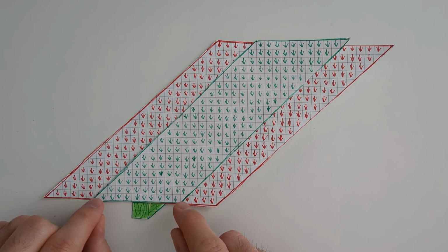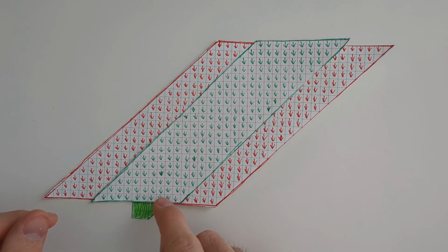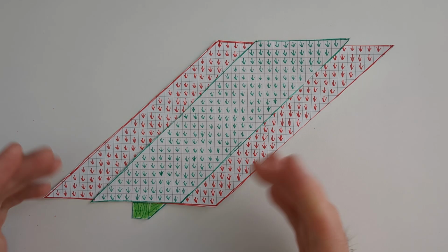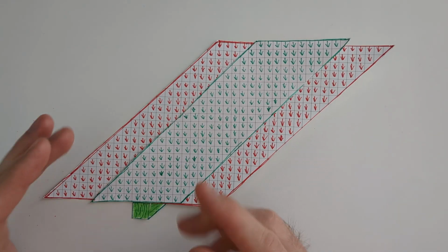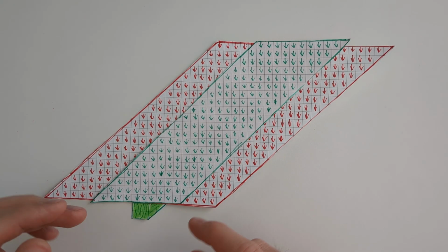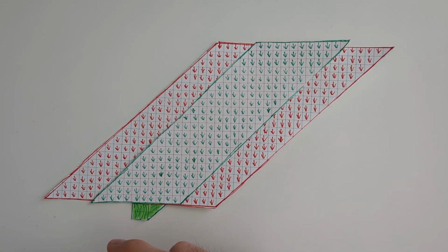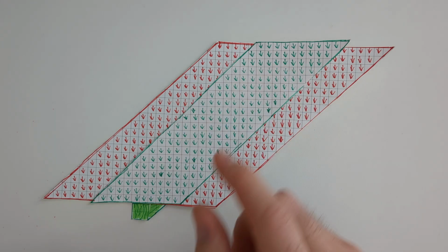So in each foot, we'll take these arrows and compress it. And you can see here, each foot is represented by the square. So in each line here, we have 1, 2, 3, 4, 5, 6, 7, 8, 9, 10 arrows. So if we compress it, that means within each foot, we'll have 10 arrows acting down. Now, if each arrow is 50 pounds force, we have 10 arrows. That should be 500 pounds acting along each foot along the beam.